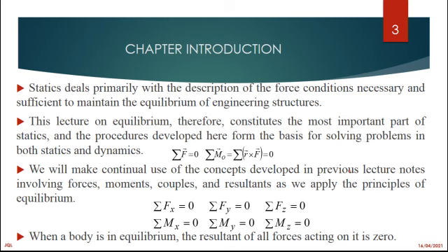Can you remember the R cross F? This is the cross product. This is the tool that we use to calculate the moment of a force about a point in 3 dimensions. But in 2 dimensions, we normally use a simpler way, which is a scalar analysis, where we just multiply the force times the perpendicular distance.